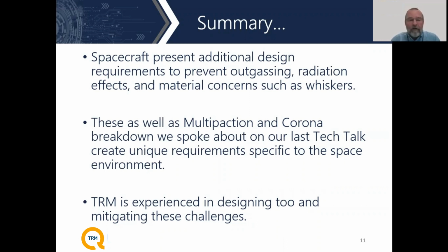And what they actually do, if you do have some high outgassing material on the satellite, is fog the lens, and then therefore make it very difficult for you to get good data. Very often they make cameras and optics almost useless because they get fuzzy, or they can also go in there and damage some other microelectronics that are on the satellite as well. So that's why outgassing is as important as it is.